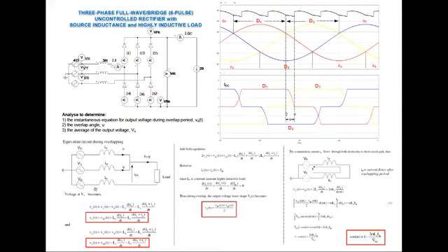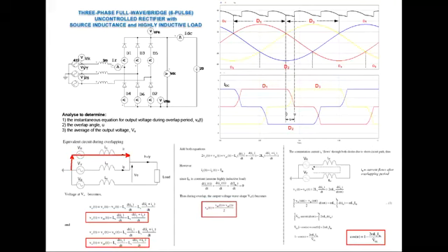Okay, so having that equivalent circuit, we can resolve two equations. One describes the loop from VR into the red phase loop, and then goes through the load and comes back to VB.